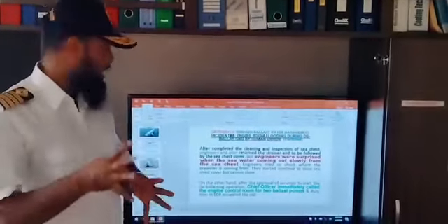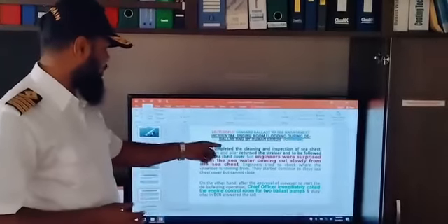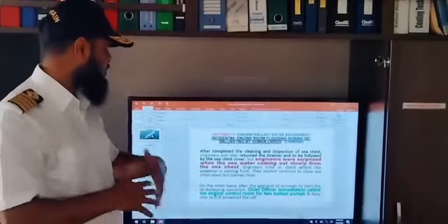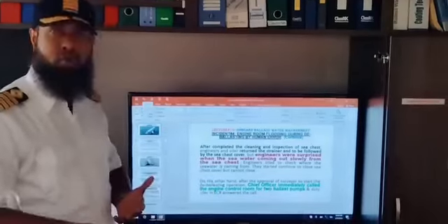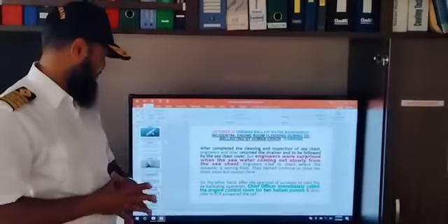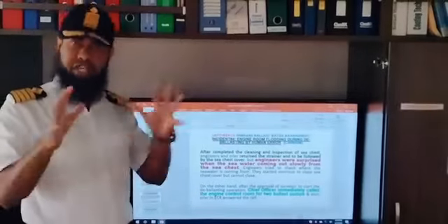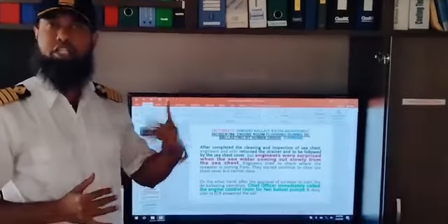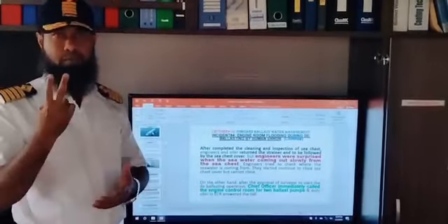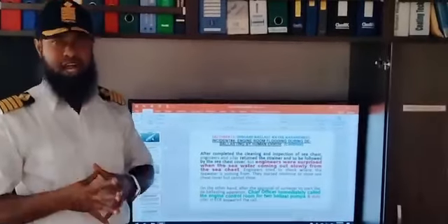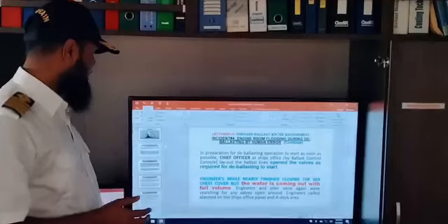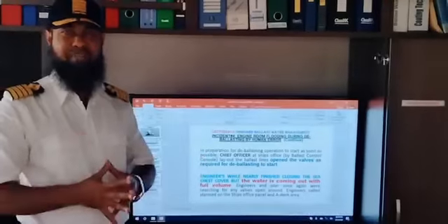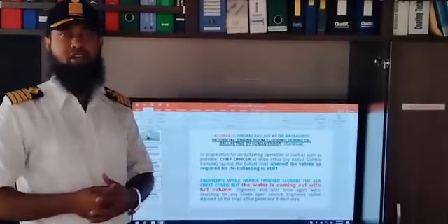After completing the cleaning and inspection of the sea chest, the engineers and oiler returned the strainer, to be followed by the sea chest cover. But the engineers were surprised when seawater came out slowly from the sea chest. On the other side, the chief officer, after finishing the initial draft survey, needed to start deballasting as soon as possible. So he called the engine room to give the 2 ballast pumps. They told him it would take some time. Meanwhile, the chief officer lined up and opened all the valves for deballasting, ready for once the engine room was ready.